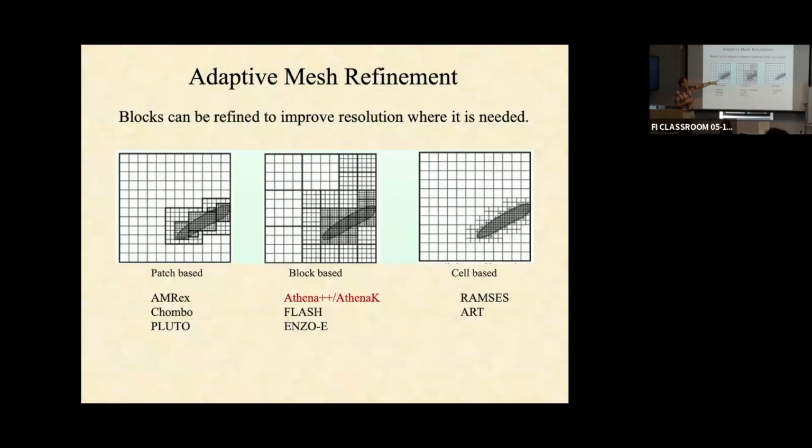And they overlap the coarser patches below because they're of different sizes, and you can't predict. You'd have these weird shaped boundaries inside your mesh. You store all the levels at once, and you just interpolate back and forth between the fine and the coarse levels as needed to cover this patch. And it has a great advantage of being the most efficient in terms of number of cells in covering, or almost the most efficient. It is the second most efficient.